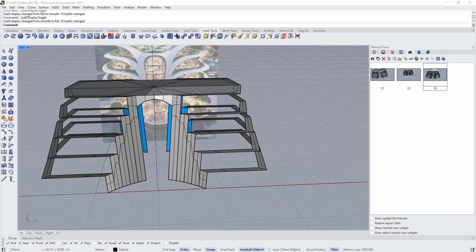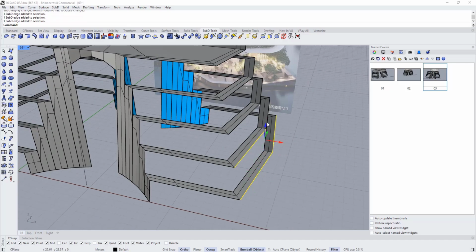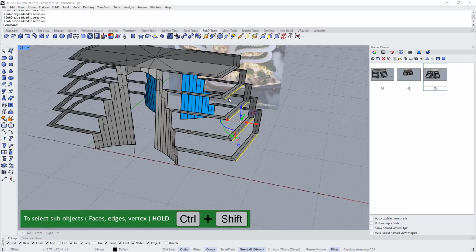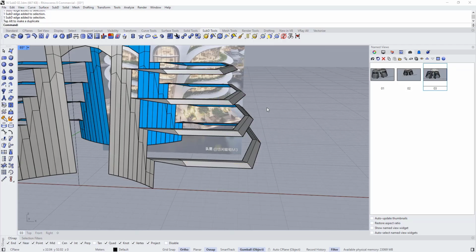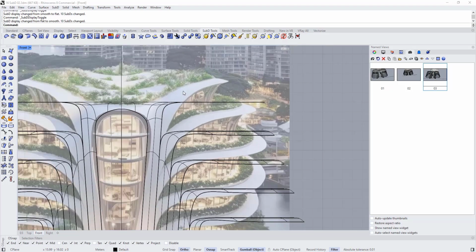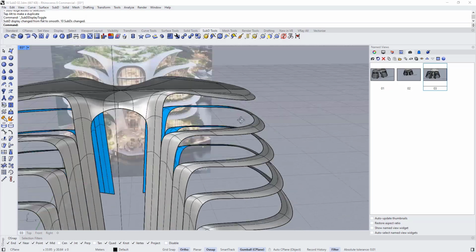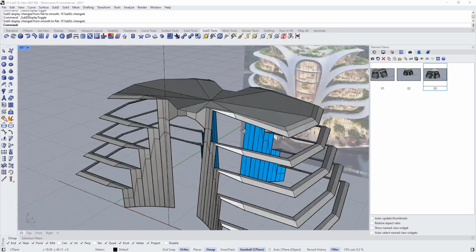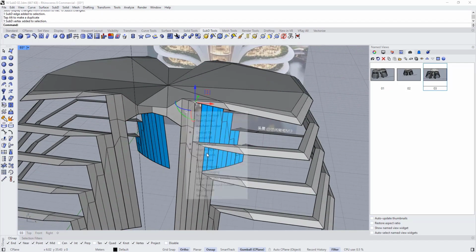Okay, now we will keep adjusting the control points until it matches our design requirements. So we can select all these edges. This one, this one, this one, this one, and maybe this one too. Put it down a little bit, something like this. Double click to minimize, and let's go to the front view. I think I might move this up a little bit, maybe something like this. This point needs to move down, but align it to object.